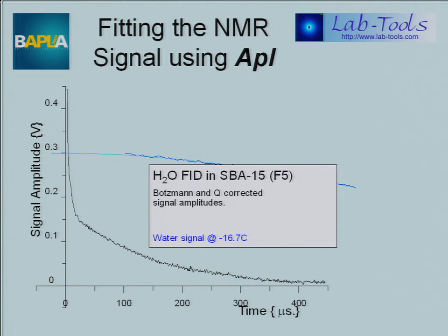This other signal here is recovery from the kilovolt RF pulse. This is microvolts of signal, looking at it following a kilovolt of RF. Do an exponential fit to this section of the data. That's our long-term 100 microsecond decay, and do a Gaussian fit to what's left over. Very easy to do in APL.